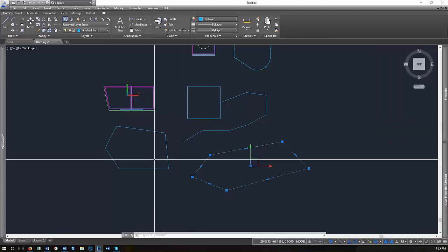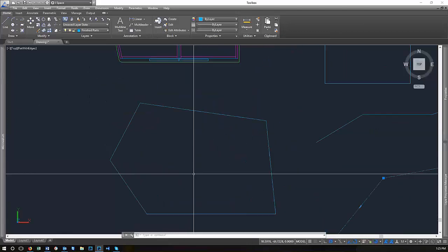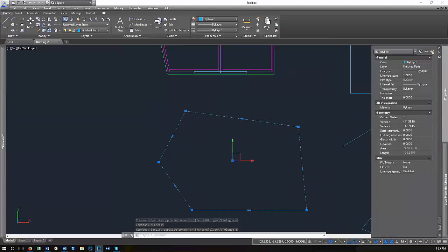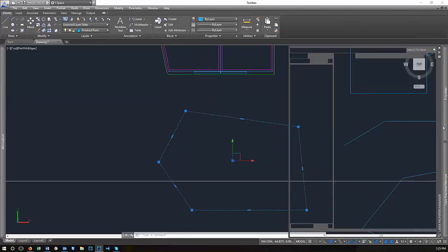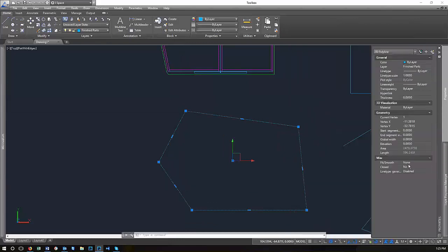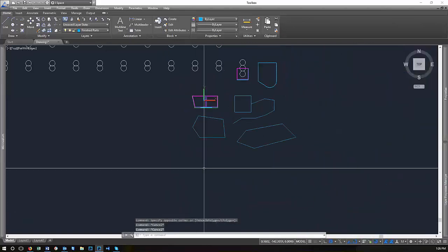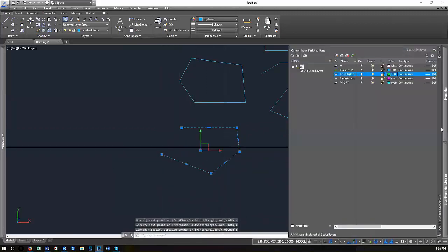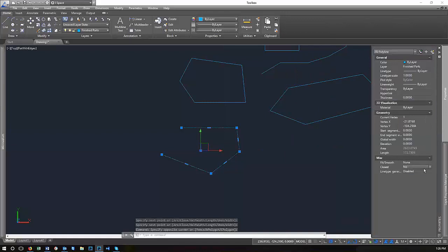So it's a closed polyline, and we want to keep track of that to find out whether or not objects are closed. You don't necessarily want to close a polyline that has the endpoint and the start point at the same place after the fact, because it will create an extra vector. So let's watch this. It starts at 1, 2, 3, 4, 5, and 6. Then 6 is at the same point as 1. If I hit close, and let me demonstrate on a different object. So polyline, click around, and if I hit close on this, it's going to draw an additional line to close that object.